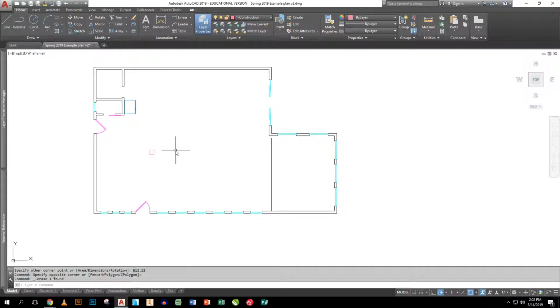The other thing I need to do is determine the distance I'm working with. This distance from here all the way to there is how far I want to span. Now, there's a couple of ways to do this. I can either use the dimension tool and work it out mathematically, or I can use what we call the divide tool. The divide tool mathematically divides a line or a line segment for us in the computer. Now, how does that work?